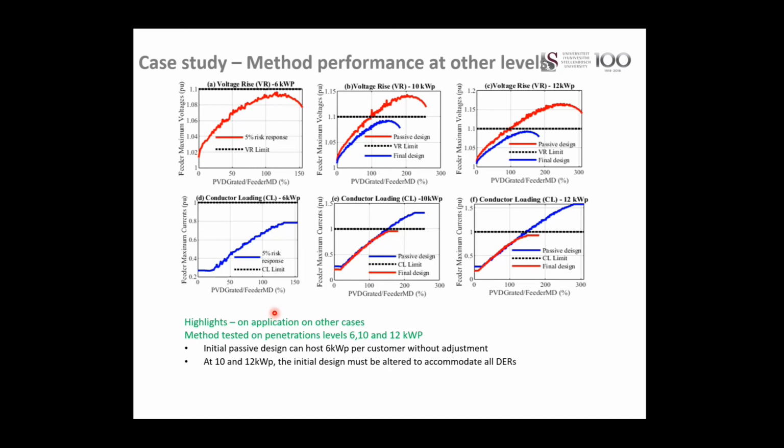But I think, Lewis, you meant that if you have the actual amps in your feeder at the highest, then you get the biggest voltage rise, which is, I would say, your best scenario when you either have low generation and low load, or when you have high generation and high load, because there will be less current actually feeding upstream into the rest of your network. Yeah, that's okay. I get you. Thank you. I now understand what you're saying.